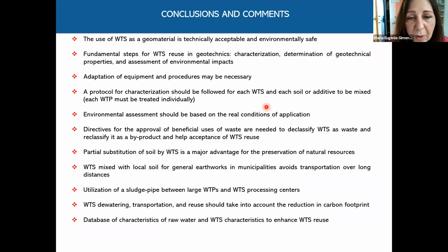WTS mixed with local soil for general earthworks in municipalities avoids transportation over longer distances. So we are thinking about reducing the carbon footprint. For large cities, we could recommend the utilization of a sludge pipe between the large WTPs and the processing centers or destinations.